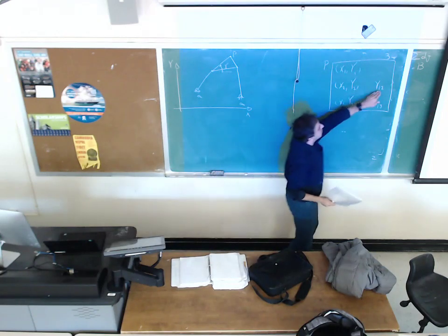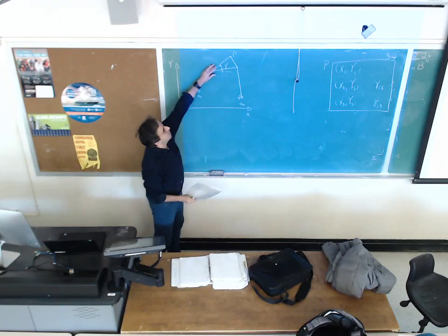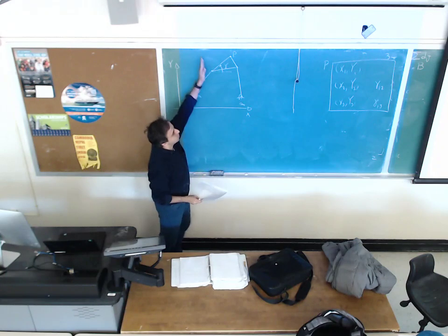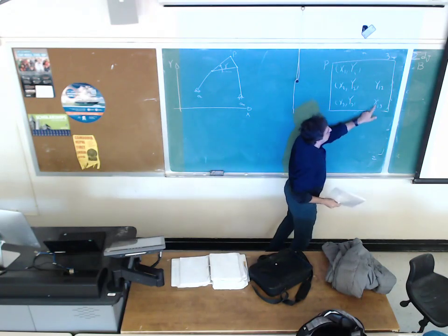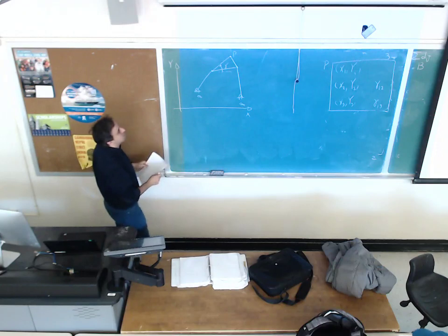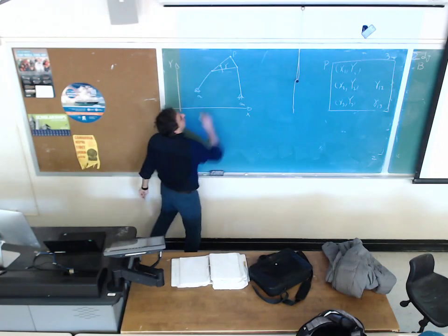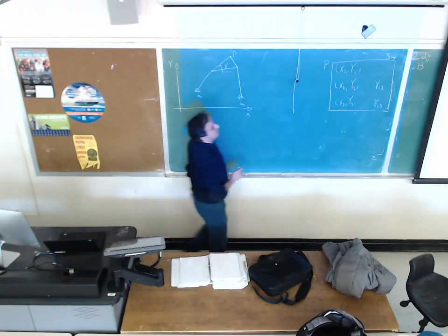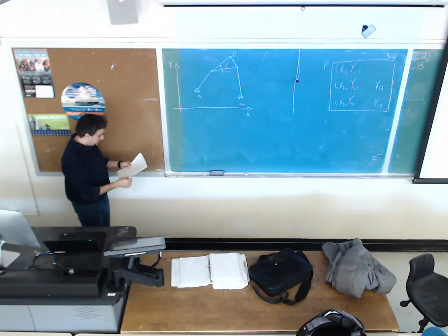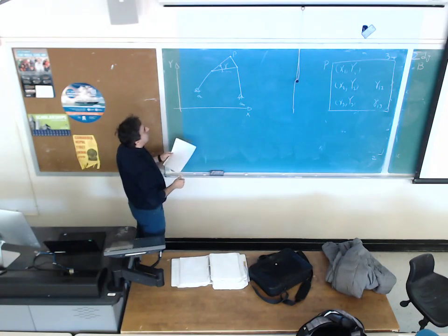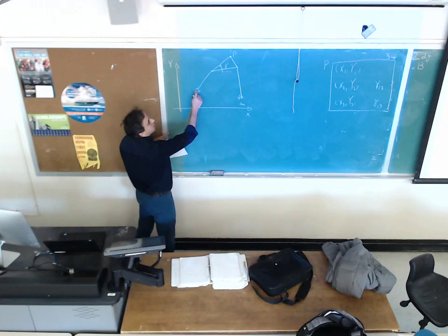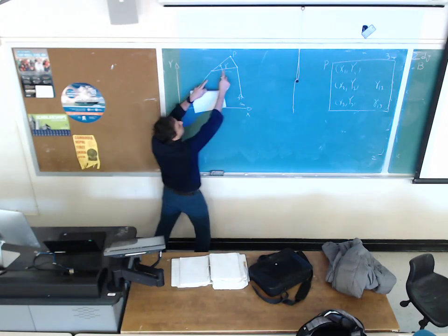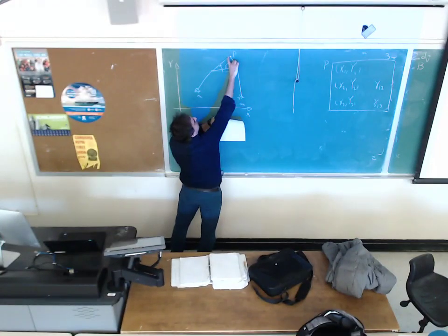And gamma 1,2 is the orientation of the coupler link, or this Turner link, from the first precision point to the second precision point. And from the first precision point to the third precision point, it must be gamma 1,3. Also, point P of this coupler should move along these three coordinates: x1, y1, x2, y2, x3, y3. So what we need is the location of O2, the location of O4, this length, this length, this length, this length, and this length.